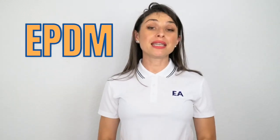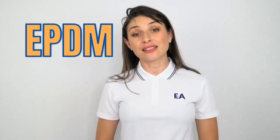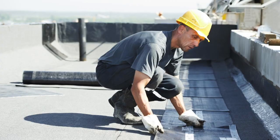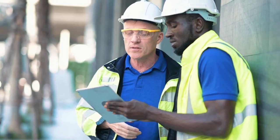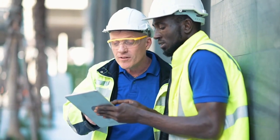Also, the membrane being black attracts the UV light. And this, of course, affects the lifespan of the material because during the heat and the cold, this material will expand and contract. Protective mats are also needed during the installation because this material can actually puncture quite easily. So this is another reason why you want to make sure you hire a certified contractor.